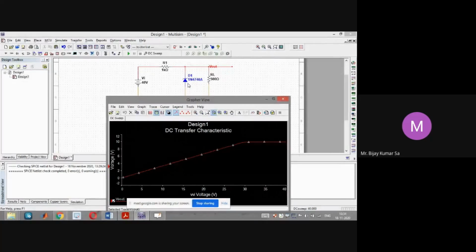Okay, and that will let you calculate the VI max that can be given at the input of the voltage regulator. If you exceed this VI max, or rather you say if you exceed this IZ max through this zener diode, because you should always keep in mind once the zener diode is on, there is some current in the reverse direction.